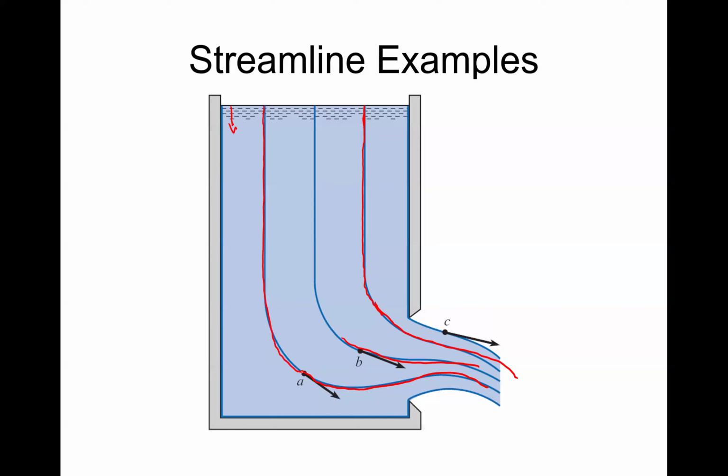The second part is something you have probably seen before in your house when you open the sink: you have a hole of this diameter, but the stream is smaller. That is what we call the vena contracta. You will see a little more of those details in the next class. The vena contracta happens because of the angles the fluid needs to go through as it enters the orifice that is causing the drainage.